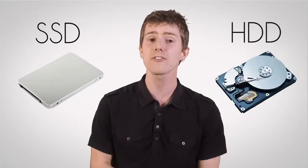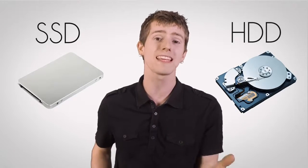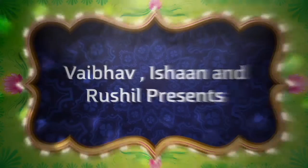An SSD is an example of something that uses NAND flash, but in spite of the fact that I just said it has reduced performance, it's still much faster than a more traditional hard drive. The only drawback here is that due to their much higher cost compared to a hard drive, typical capacities for SSD devices are tens or hundreds of gigabytes in portable devices, or up to 1,000 gigabytes or a terabyte in high-performance computers. NAND flash is also used in low-cost products like USB thumb drives, but the chips used for those are much lower performance and not capable of as many program erases.